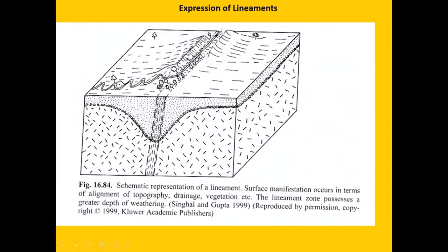So that simply indicates there has to be a structural or subsurface control, which guides the vegetation to grow in this fashion, because the vegetation gets nutrients from that dike. Suppose the dike is a dolerite dike or basalt dike; it's getting its required nutrients from that basalt horizon only. Side by side it doesn't have those nutrients, because the rock is not present. But here it's getting the required nutrients, and that's why the plants are allowed to grow, continuing in this linear fashion. If naturally occurring vegetation happens to be in this linear feature, there must be some structural or lithological control.